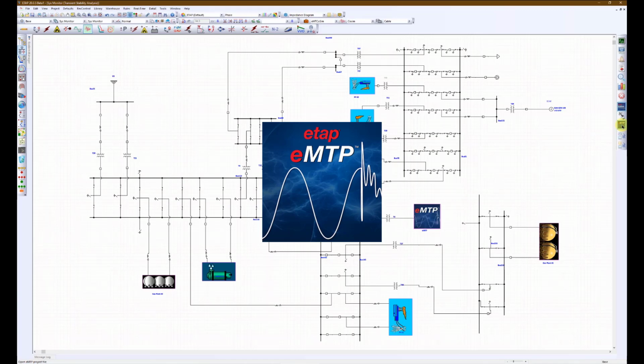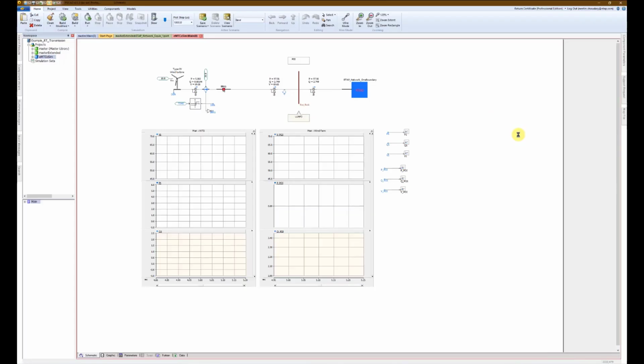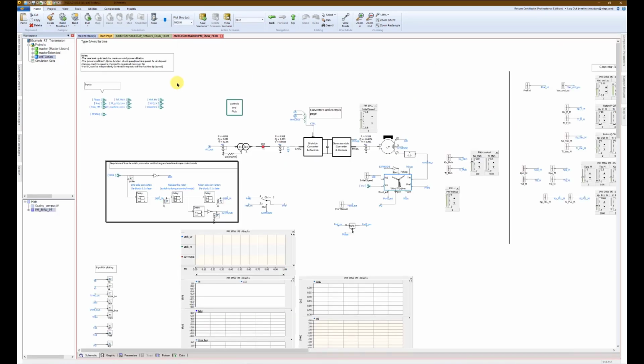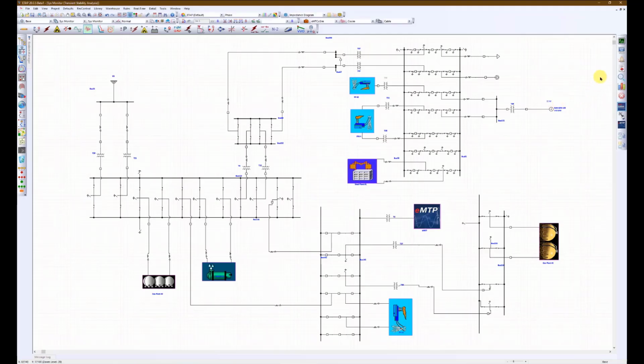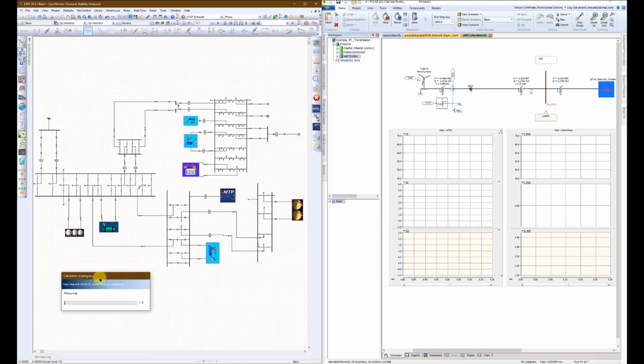To initiate the co-simulation, we launch the associated EMT project in the eMTP application. Type 4 wind generators with high fidelity models are used in this wind farm. We can see that the 20 WTG units are modeled in the network, and the blue block represents the dynamic model of the entire phasor network. Let's run the transient stability simulation with the eMTCoSim mode enabled to start the co-simulation.